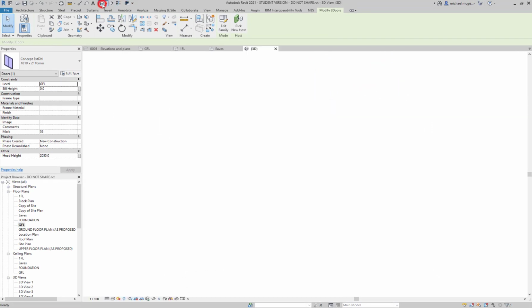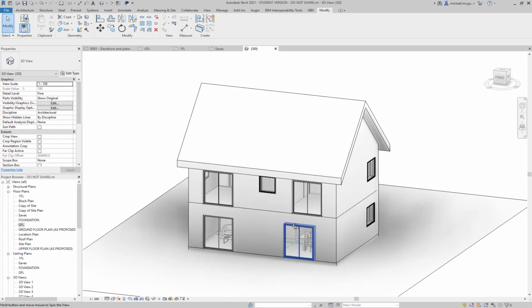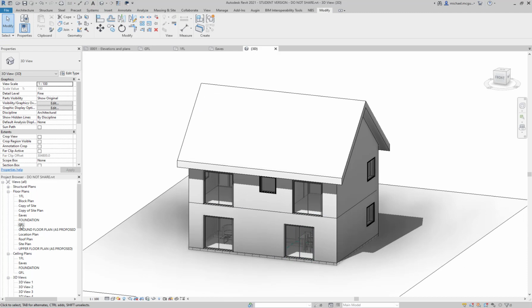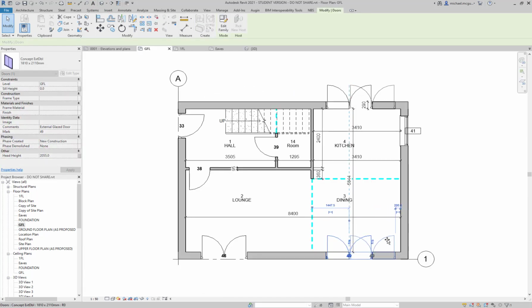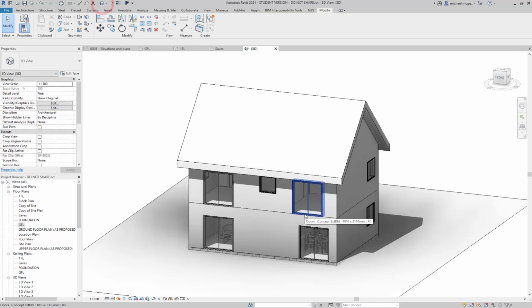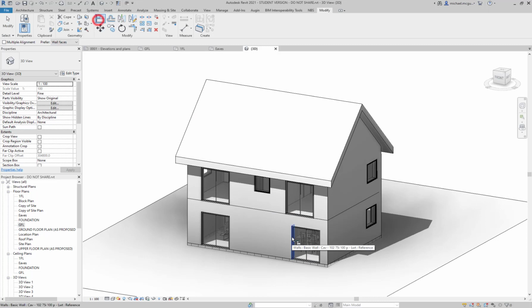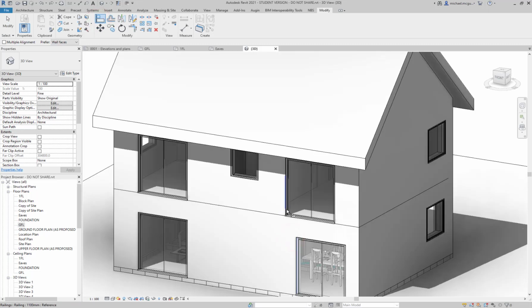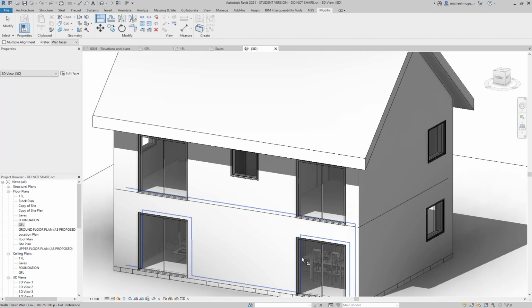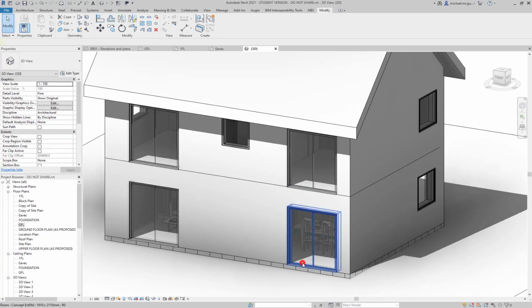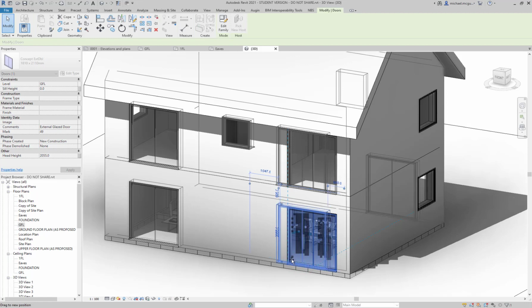You can also use this command in 3D. So here we can see that the downstairs is not aligned to the upstairs. Again, if we move this across and move to 3D, the upstairs door is not aligned to the downstairs door at all. So choosing the Align command, this time I'm going to use Tab and choose the wall reveal downstairs, and then find the wall reveal upstairs and select that. Again, remembering to lock the constraint so that if we move one, now the upstairs and the north door all move at the same time.